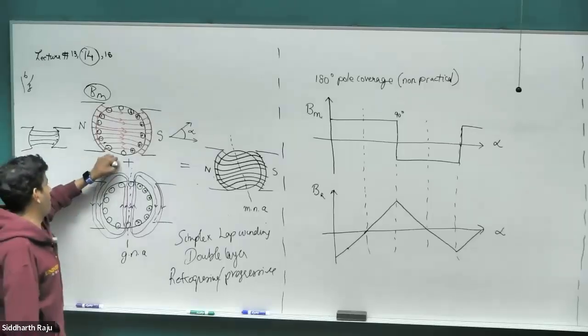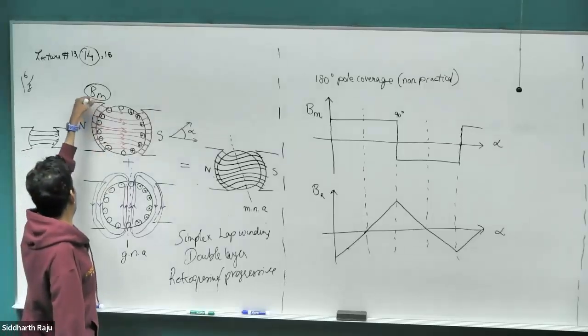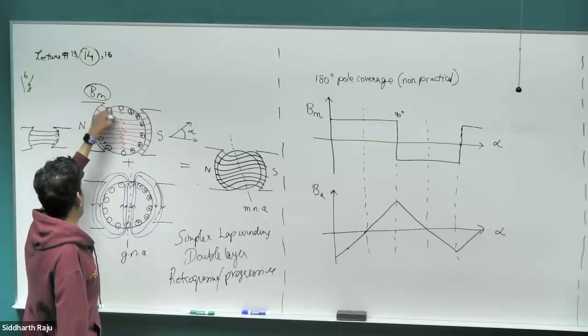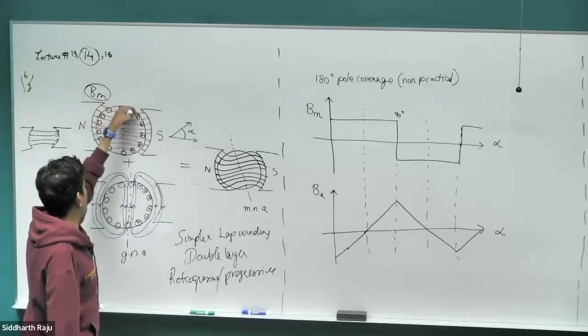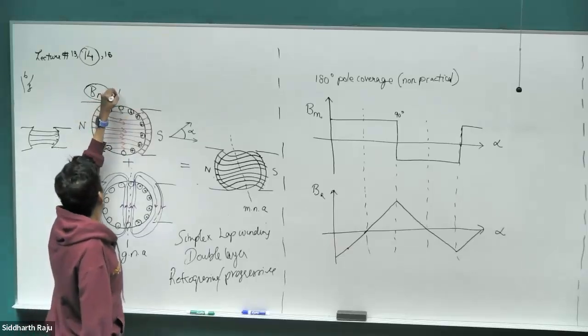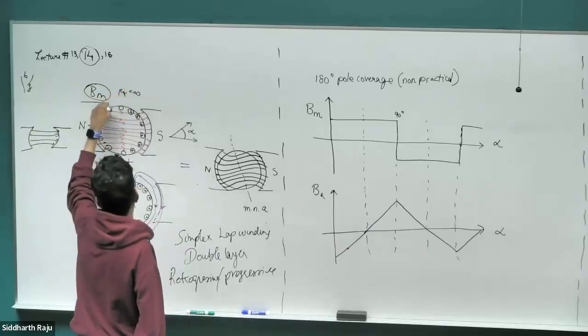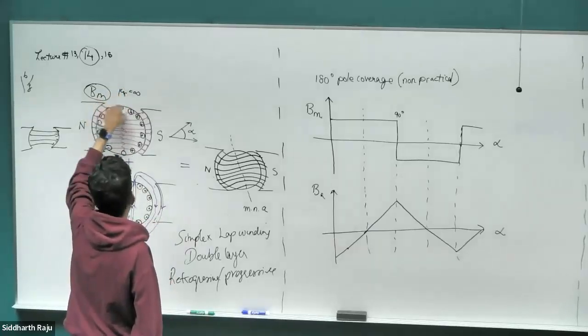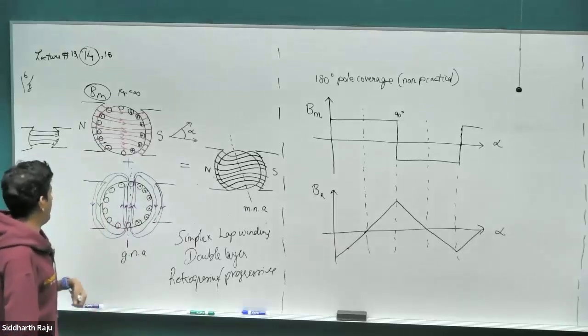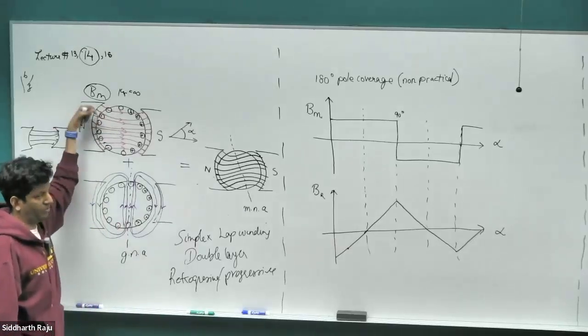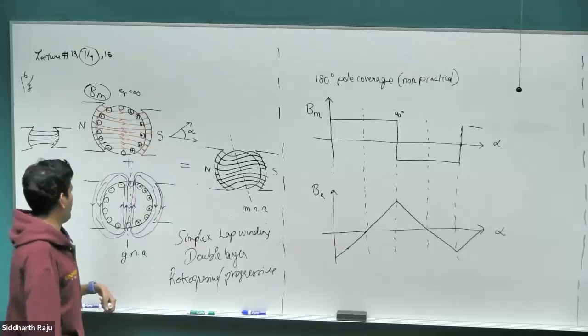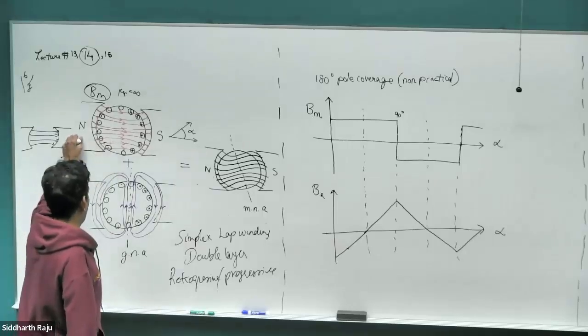But the minute we put in the iron, the perpendicular direction going from the pole to the iron leads to the shortest reluctance path, because through the iron we assume the permeability is infinite. So here there is no MMF drop in the iron, there is only MMF drop in the air gap. The least reluctance would be the perpendicular distance, which is the shortest distance between the two places. So this is the magnetic field due to just the magnet alone.